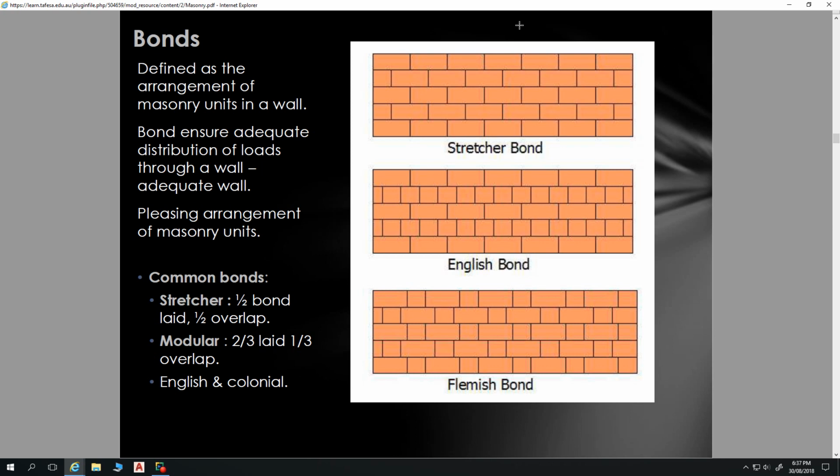working together. And by the way, bricks apart like this is called cavity brickwork. Bricks together is called double brick. And that's where you use these types of bonds. So your double brickwork happens like that. So I've got two stretches here and a header. So if I turn that around like that, I end up having two stretches and a header.